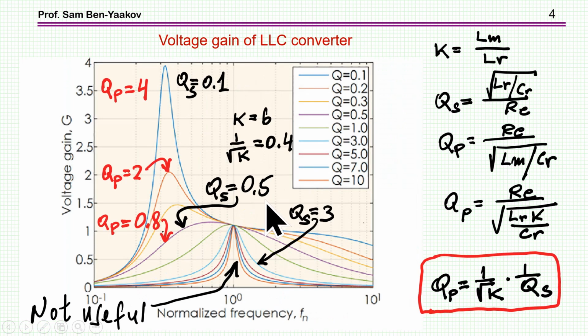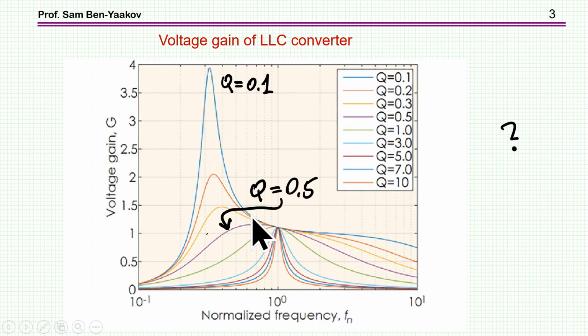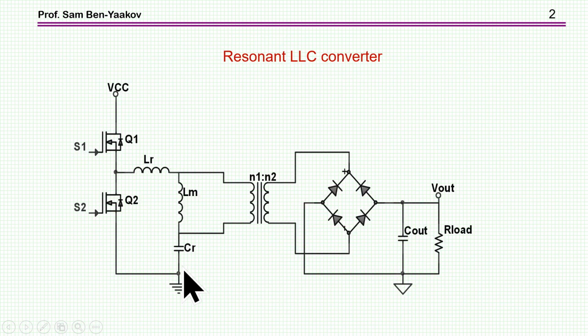Now I've shown that there is actually a misconception here, a mistake I would say, in that the Q is related, in this particular presentation, which is very customary, and which you'll always find in, say, application notes and papers, to the series resonance of the unit, that is this resonance between here and here.